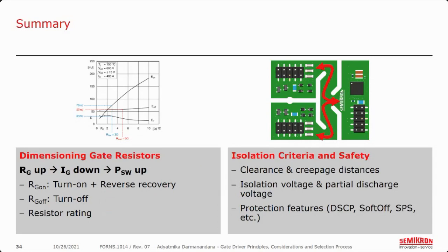Lastly, Semikron offers dynamic short circuit protection and soft off to safely turn off the IGBT in case of a short circuit. Other features like dead time, undervoltage lockout, and short pulse suppression are all available in each of Semikron's driver products.